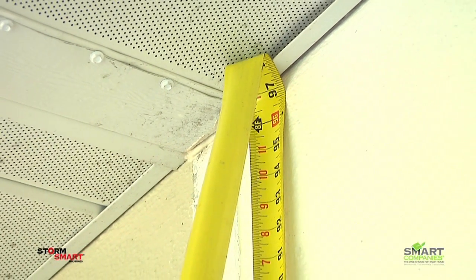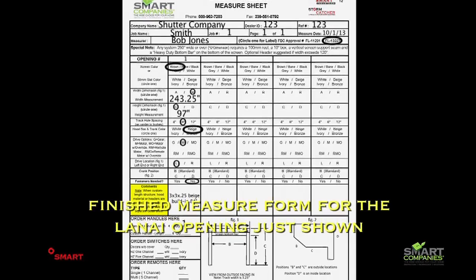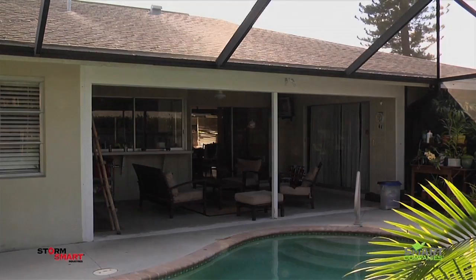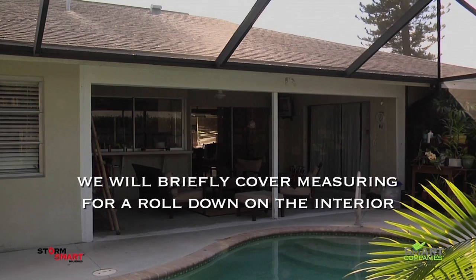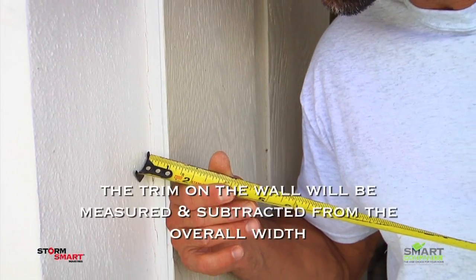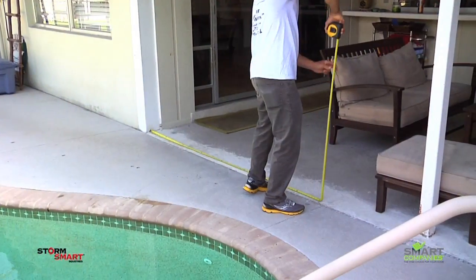As before, once the measurements for this opening are filled in, fill in the rest of the info needed to complete the order for the opening. Next, we will measure the same opening for the rolling screen to be installed on the inside of the lanai. Note that we must account for the trim on the wall. Then, we measure the width and height.